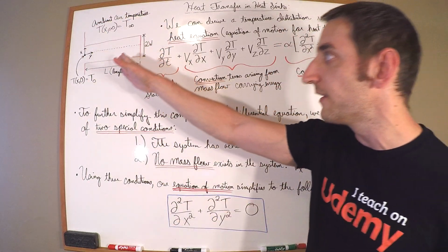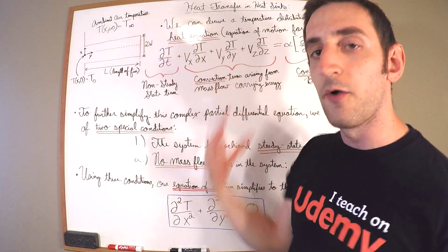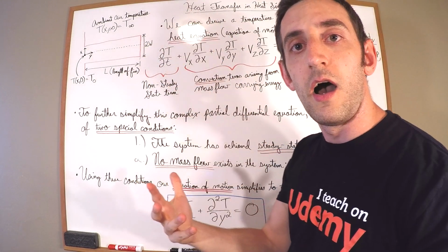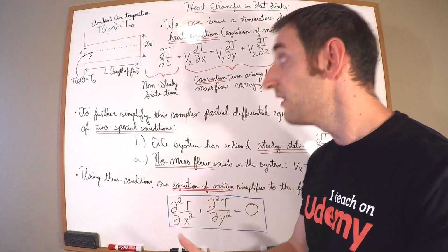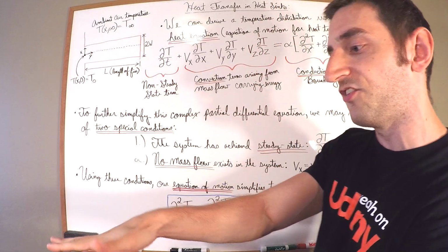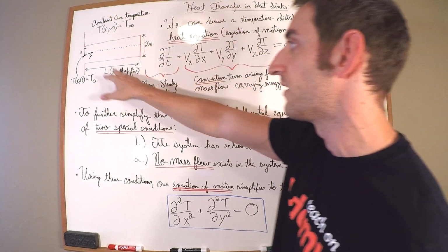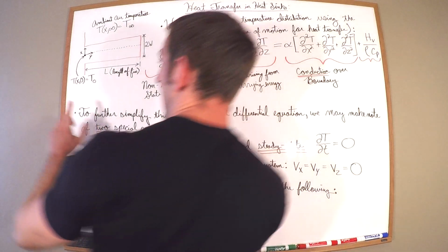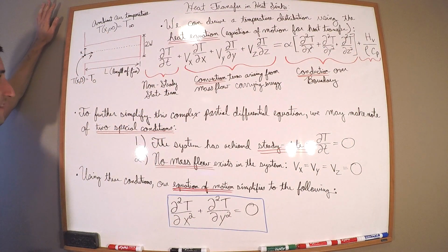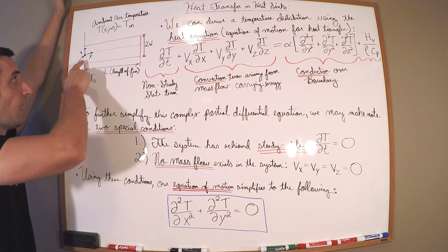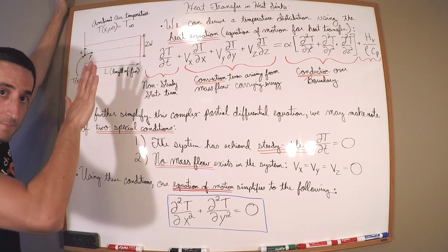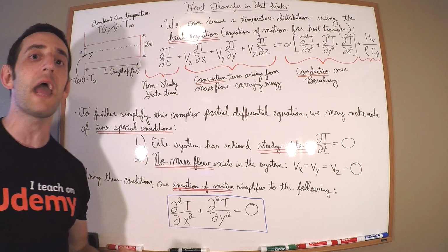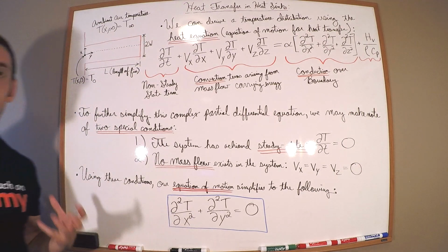Okay, so what I described here is one single fin. I'm going to assume it has a thickness of 2W. W is sort of hyphenated for width. And then it's going to have some kind of length at which it comes up above that base plate, which we're going to signify as L. Okay? So what you notice here is that I selected our axis to be in the middle of the fin. Now, as we go through the boundary conditions, that's going to elucidate why I made that choice and why it simplifies our analysis.